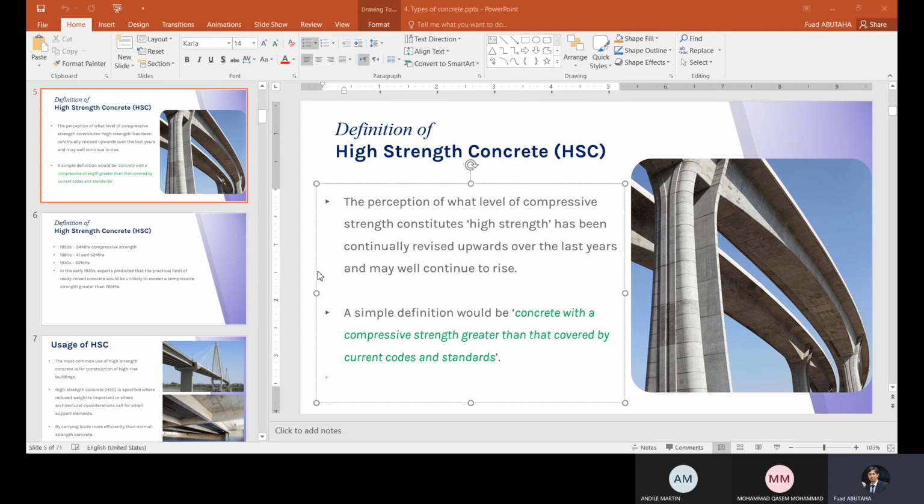It's okay, it's easy. But if you want to design concrete that has high compressive strength, and these days high compressive strength might be defined as more than 80, more than 90, and even higher than 100 megapascal, there is no standard method that you go step by step, and at the end of this calculation you get to know the mix design: how much cement, how much aggregate, and how much water to mix so I can get the high strength.